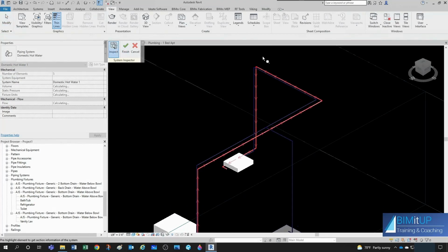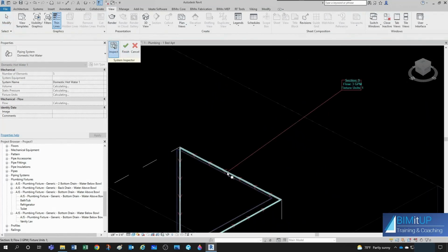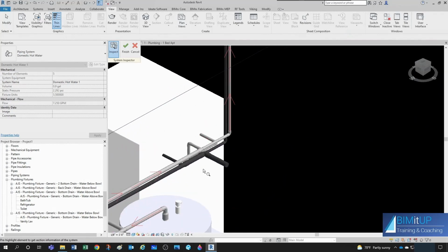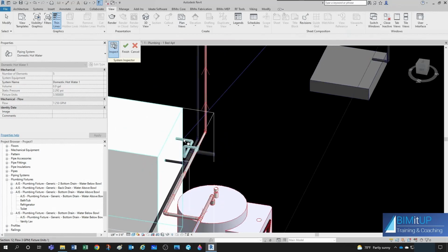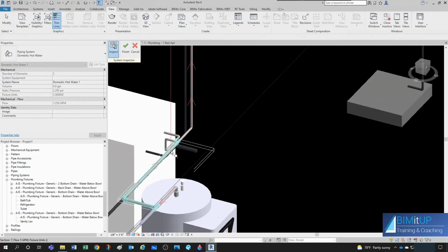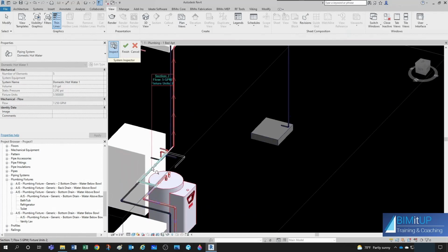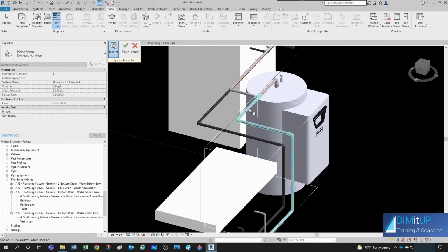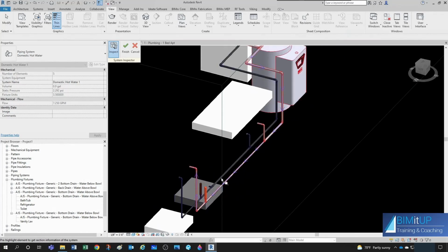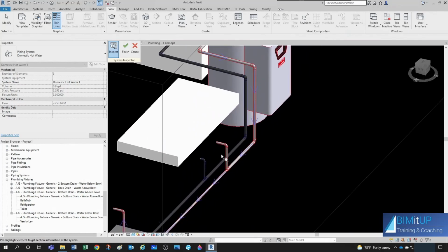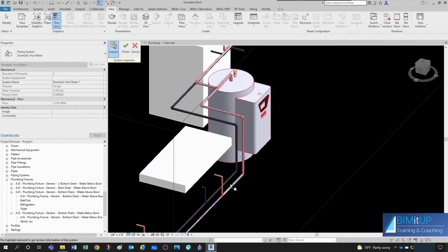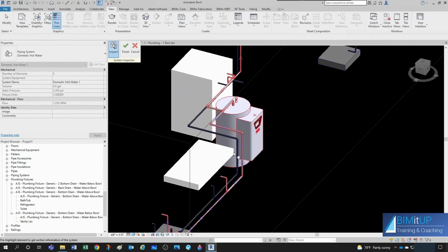And then we're going to inspect. Let's see if this makes sense. We have one fixture unit right here. That's perfect. So now we keep going, and now we encounter our washer, which has one fixture unit as well. So it would make sense that here we have two fixture units, and that's exactly what we have. Then on the other side, we have here one fixture unit. That's perfect. The toilet doesn't have hot water. Then this guy here has one fixture unit as well. Actually, 0.5 fixture unit. So here you have 1.5, which makes sense.